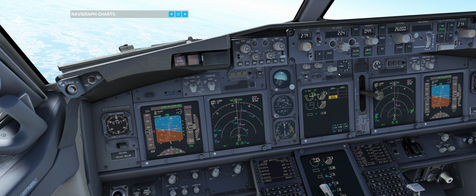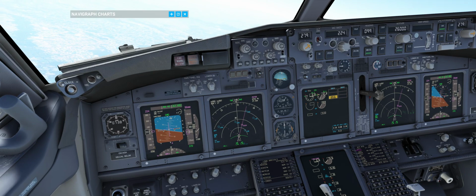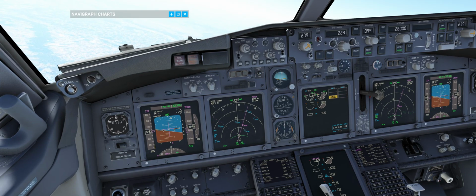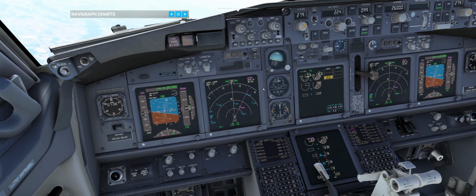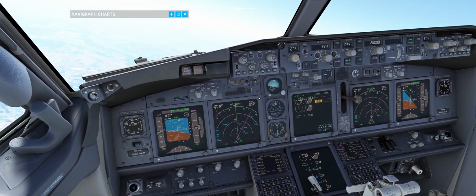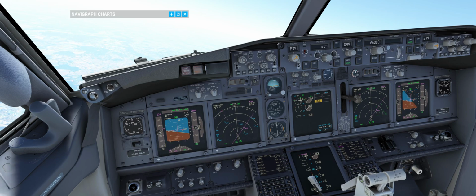The bank angle 15 is only limited when you have engine failure after takeoff, just after V1, and you need to perform the turn, and you have V2 less than plus 15. In this case we are using a bank angle of 15 degrees. But anyway, we are on our altitude, flight level, sorry, right now, so we are adjusting thrust of the live engine in order to keep the desired speed, and we may proceed with the turn.